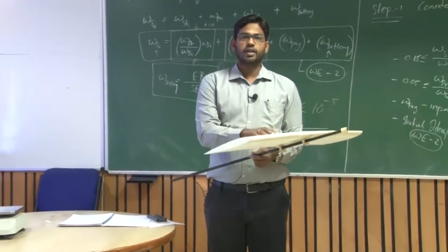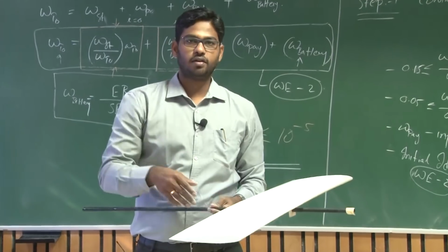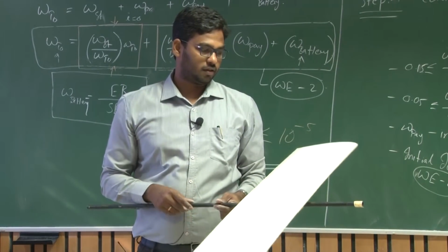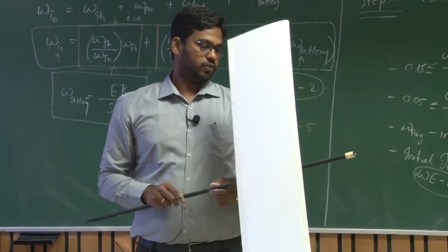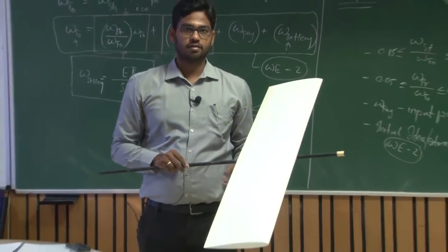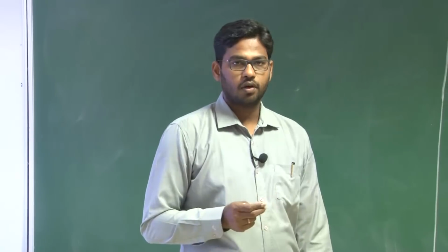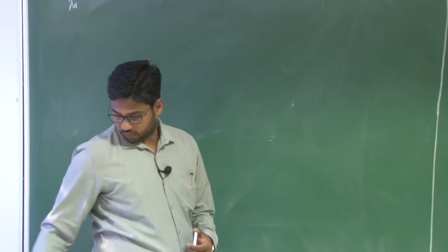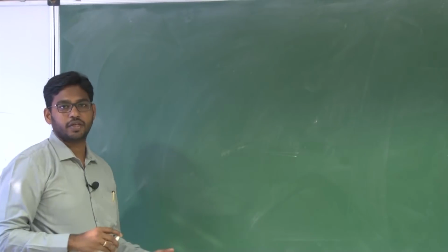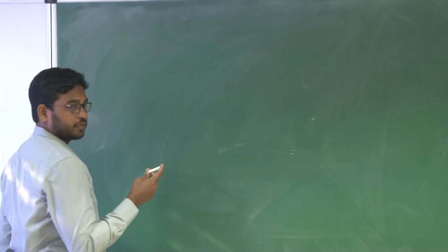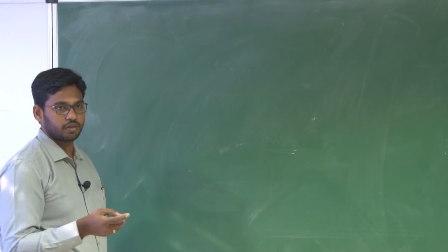How much weight can this wing carry? Or with this wing, what can be the weight? What is the maximum limit of the weight with which I can still fly, right? We'll address that by wing sizing. Now, let us write down the final steps: how to find the weight of the battery, or the initial weight estimate of a UAV as per the mission requirements.